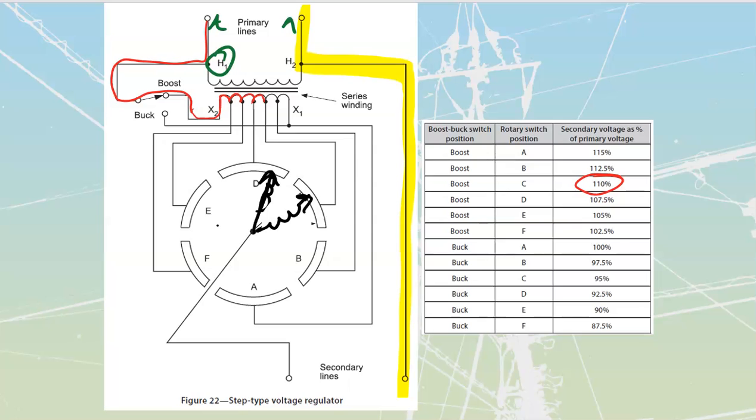What these would allow me to do is divert my main current. So my main current would still be coming in on here and then going down and through that. And then I'm also going to have a smaller current. This winding here is still 2.5% of my primary lines. If my primary lines are 25 kV, that's still a significant amount of voltage. And so I've got these two reactors over here that are going to form an opposition, a counter EMF, so that we don't directly short that out as we're transitioning from one to the other.